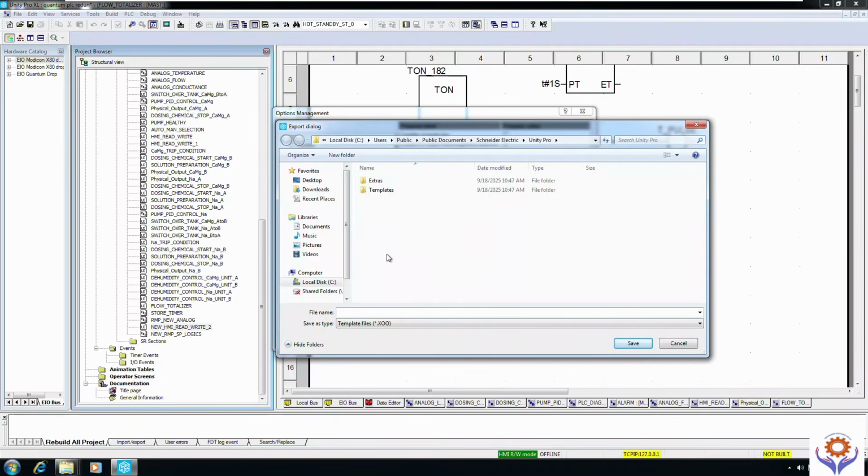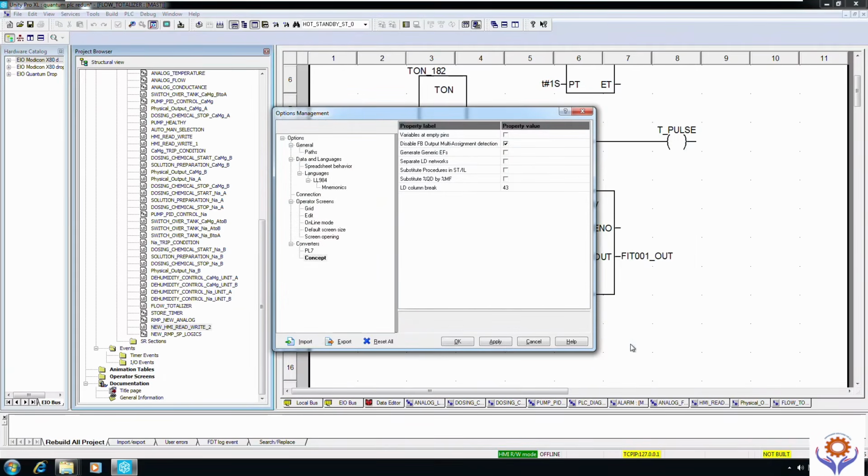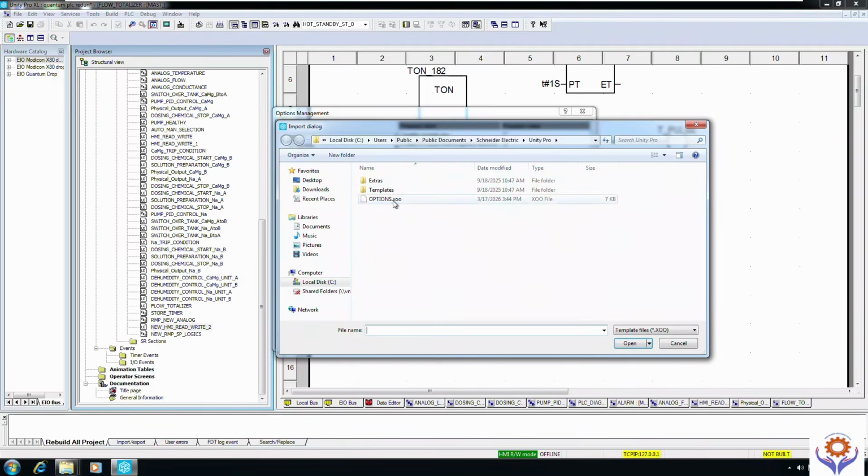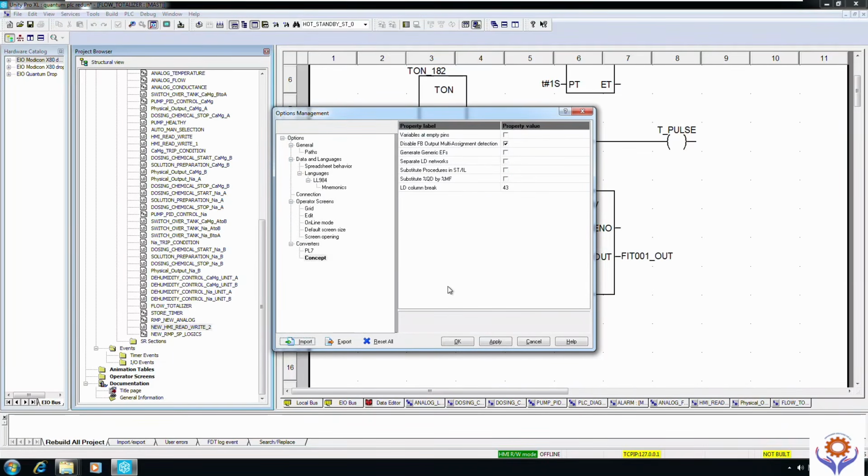And also further down you can see here you can export this complete project setting options. Once you export, you can utilize it. Now I'm going to export this option with the name options. This is an .xo file, and whenever I need to import it for another similar project, I can directly import like this. Just double click and import and select this XO file.